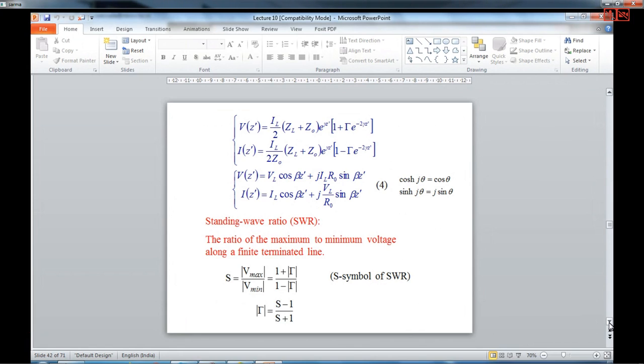So reflection coefficient is a complex quantity which is having amplitude and phase, and the phase of the reflection coefficient changes along the transmission line with a simple equation, a linear equation, y equal to mx plus c type of thing, whereas the amplitude we normally consider to be same all along the transmission line because we use the lines which are very low loss, considering them as lossless lines.